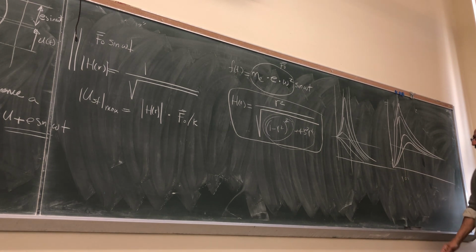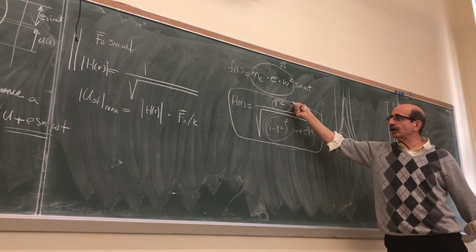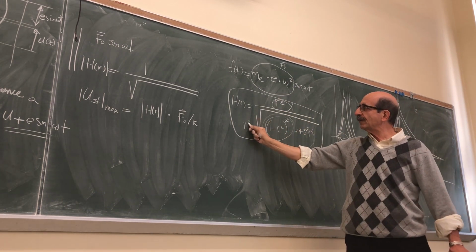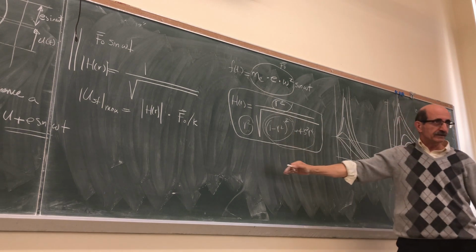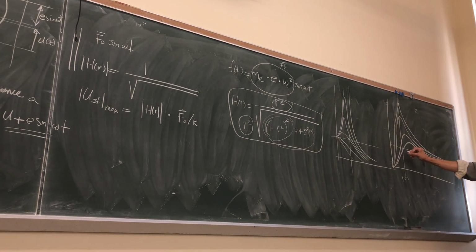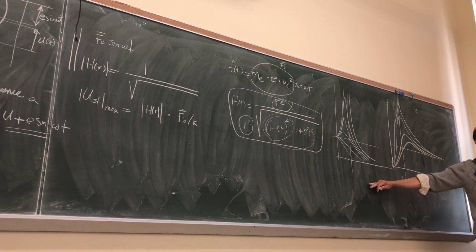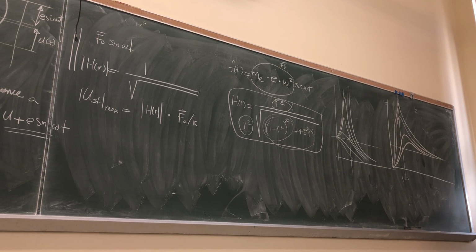Not only that, as r goes to infinity, mathematically you have r squared, take r squared out here, so it's a ratio of 1. So the limit approaches 1. In other words, there is no way under rotating unbalance that you can ever get below the maximum static displacement. At the ultimate level, at best, you would approach the static displacement.